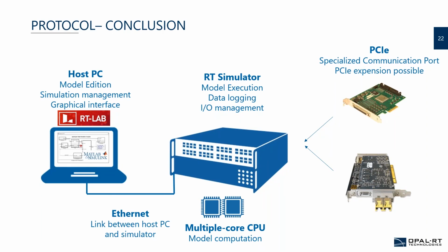If you need more than 4 cards in your system, we always have the possibility of a PCI expansion. We have other add-on accessories to add a bus of PCI that can go up to 11, and we can stack them as well. So there's really no limitation on the number of communication cards you can have in the system. That concludes my presentation on the OPAL-RT offer on the AFDX and the ARINC.